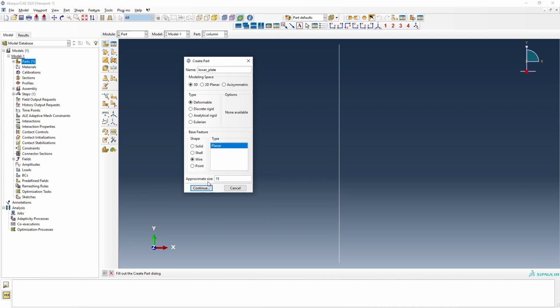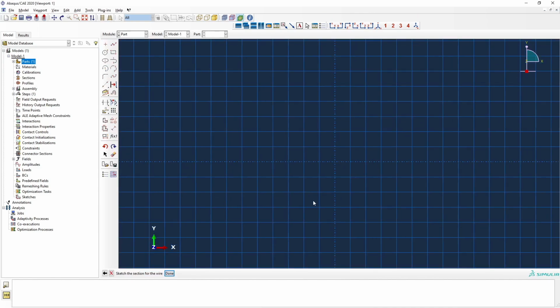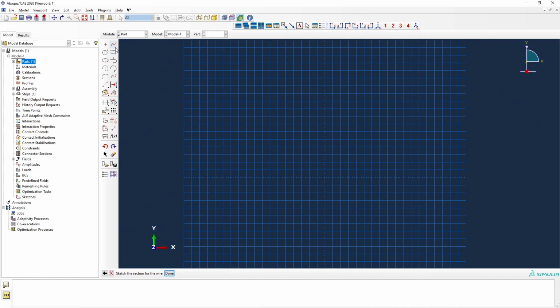So we can make this maybe 1800 as the sketching size dimensions, and then we first create the lines. The first point for the line is negative 375 in x, and then 0. So it will start from here, and then it will go 375 in positive x and 0. So we have this in column, then we can accept with the middle button, and then cancel the procedures, and